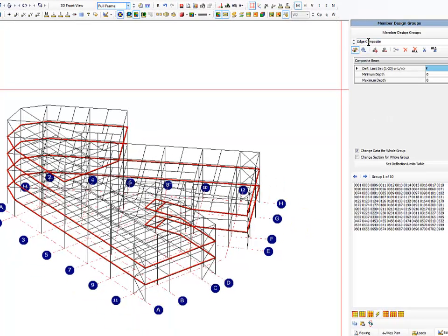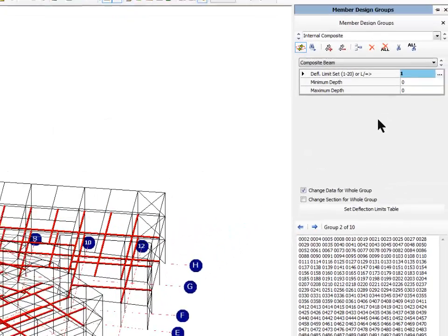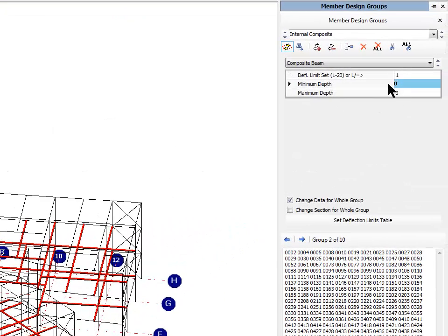So we're able to very quickly go in and then obviously set. And we could turn around and say, well, actually we want a minimum depth of section of say 200, and we want a maximum of, if it's a 457, probably 480 would be close enough, or just below 500. So that will make sure a 457 can work, but not a 533, and that will automatically drop out for all those sections and keep it nice and shallow.